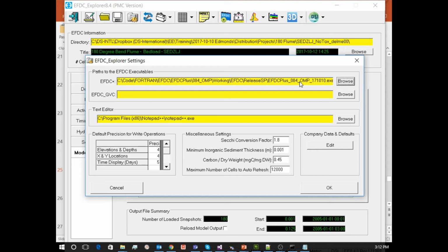Now, because that's such a common problem, we changed the heat exchange code in the EFDC, lots of changes, but one of them is we accumulate heat exchange until it reaches a certain critical level and then roll it into the actual heat exchange between the sediment bed and water column. So we just accumulate it, and that helps us get around that issue. But for those kinds of processes, kinetics, anything that has a rate of change that is really small relative to the domain that it's going in and out of, you can lose that information in round off. And that's what happened here.